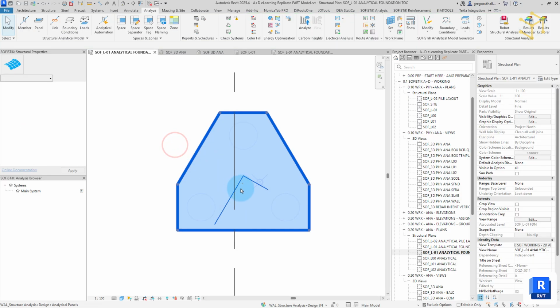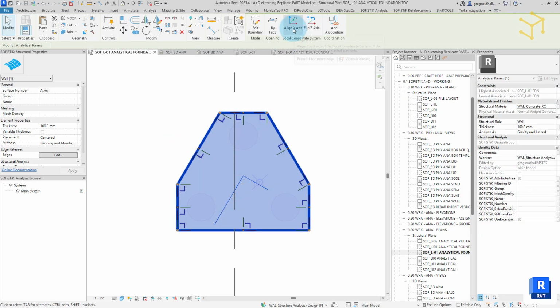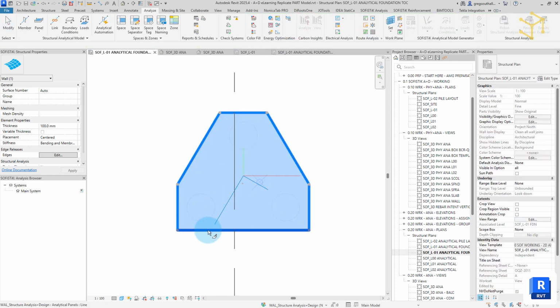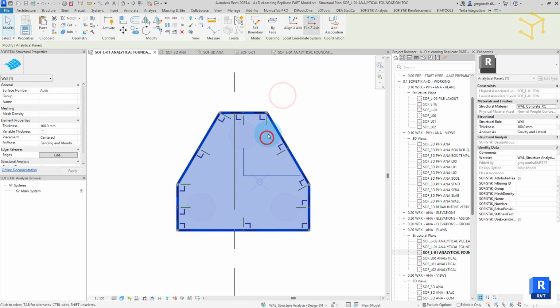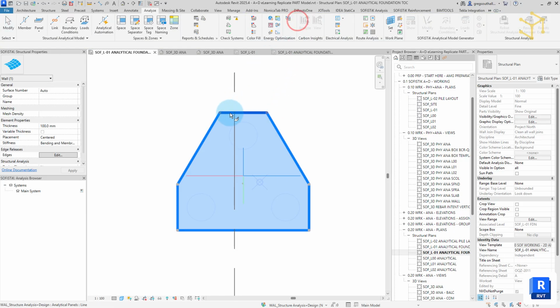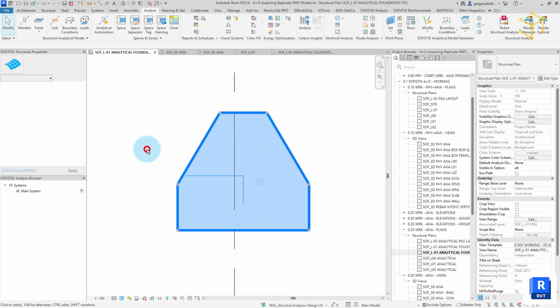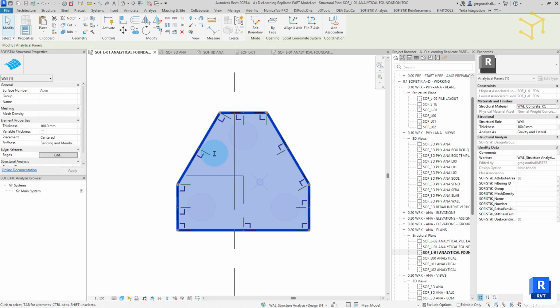We can select the Align x-axis and then select an alternative line to reorientate the axis. In addition to the local Z direction, the axis directions are important for slabs and walls, but as we'll not be conducting any design of pile caps directly inside SOFiSTiK, this is not important as we only require the pile caps to act as analytical elements to distribute forces from the columns into the piles.